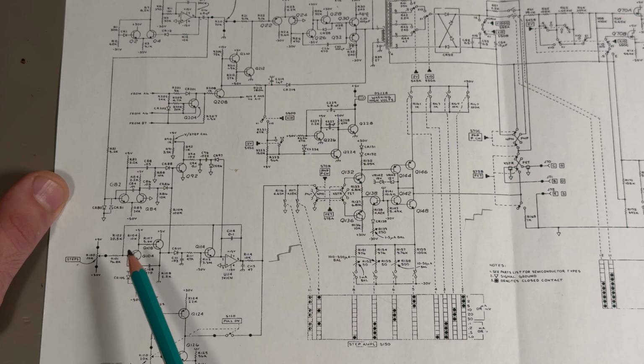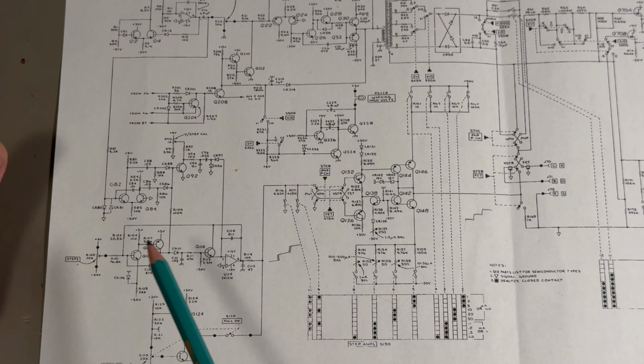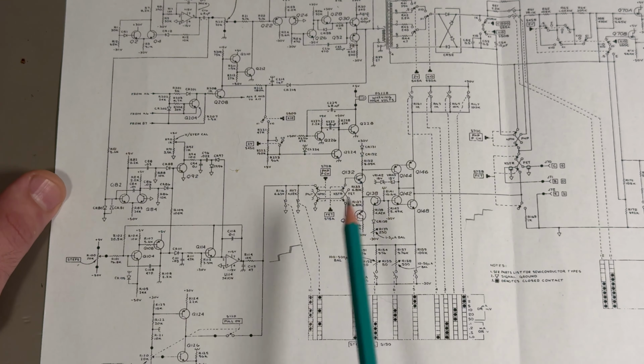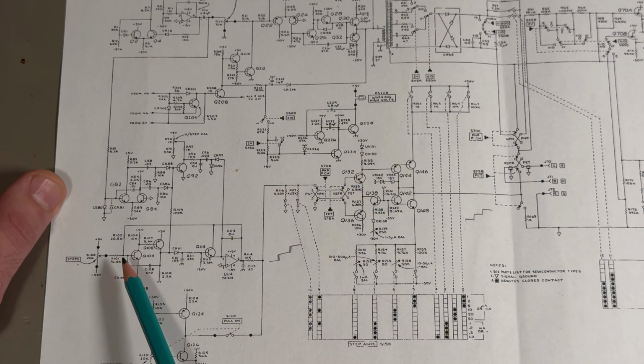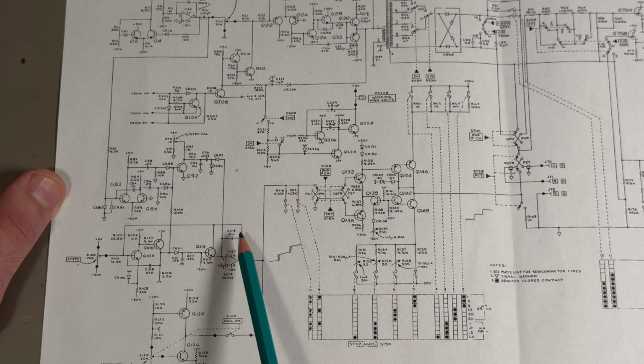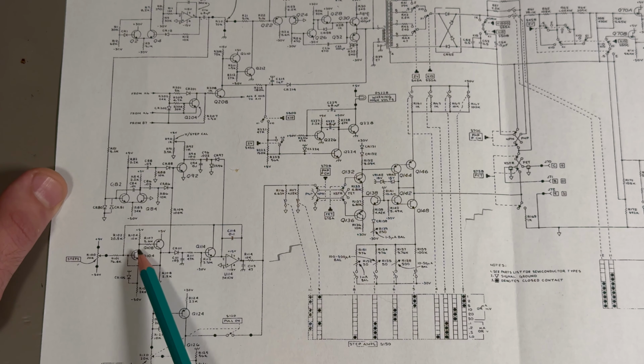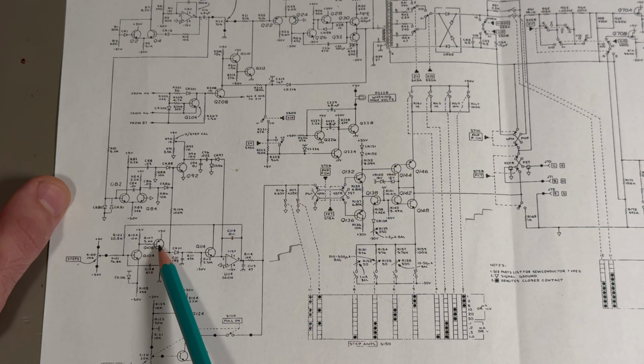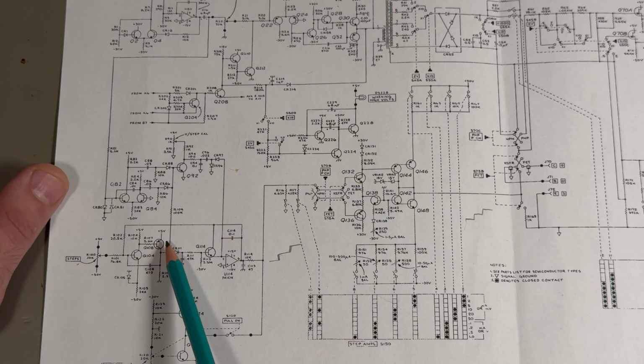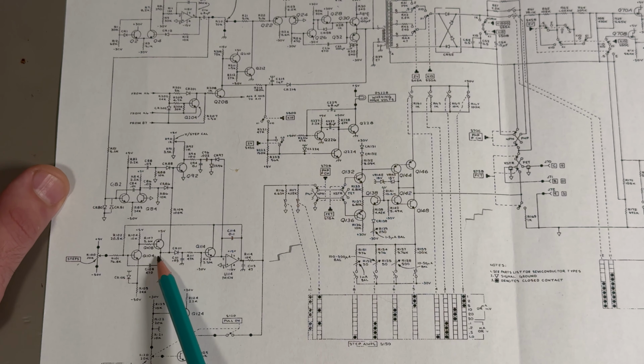When you've reached the preset level of steps, so the number of steps that you want to draw the characteristic curve for, there is a comparator here that samples the output, and this circuit is sort of like a one-shot. So Q104 gets driven, it conducts, it pulls the base of Q108, which is a PNP, down, which makes it conduct, which hits a small pulse of current through C108, which is 470 picofarads.